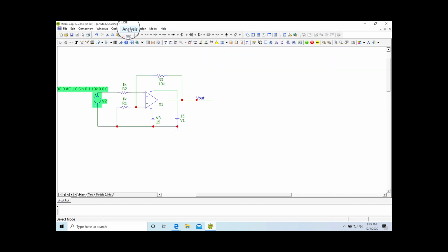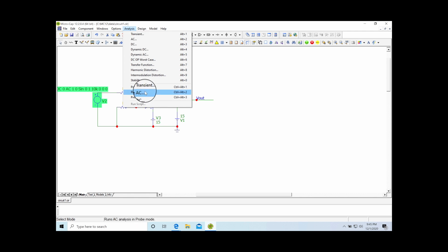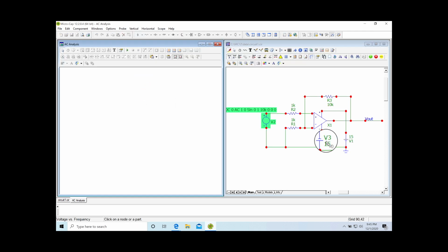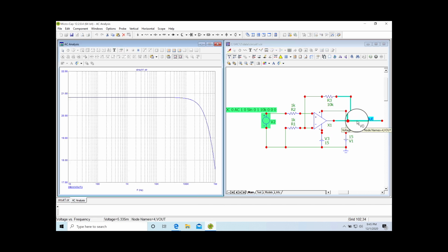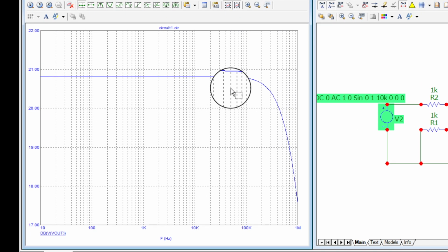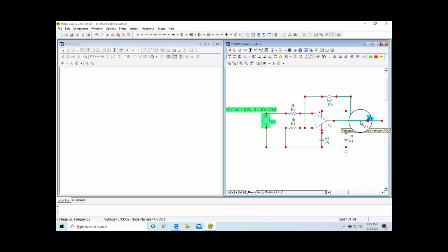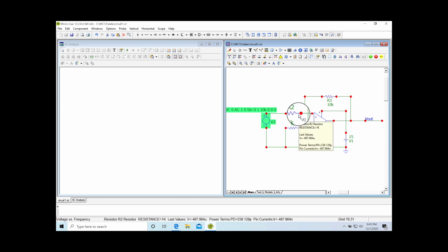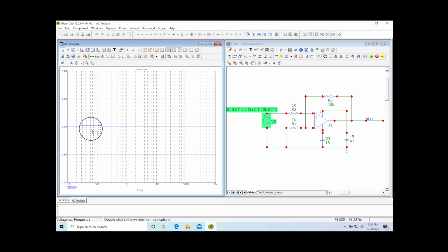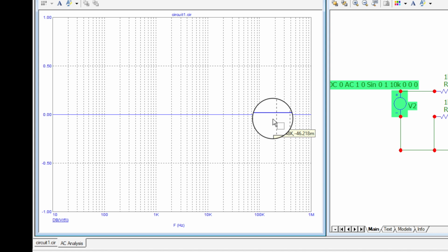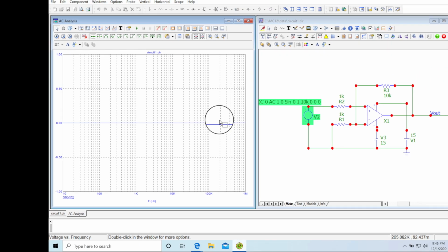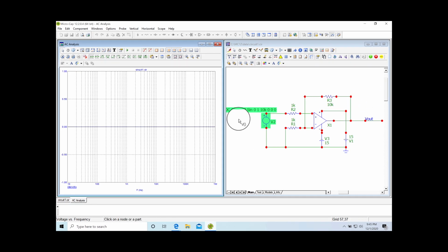All right, so that's the transient, right? That's what we were looking at before. Okay, now if we come back here and look at the AC analysis, click on that guy, and there's our gain. And over here, this guy was here. If I click on this guy again, click on this guy first, even if I go to the other side resistor, it doesn't matter because the impedance was so high, it's the same voltage, right? But if I click here, its gain is 0 because we got 1 volt coming in. Log of 1 is 0, and 20 times 0 is 0. So there we go, guys.